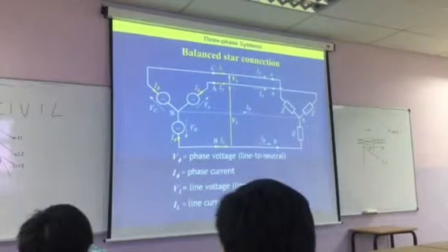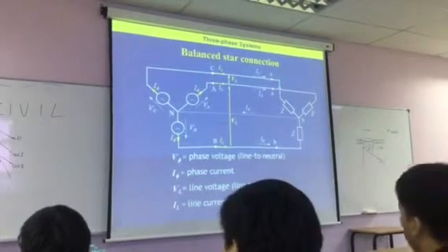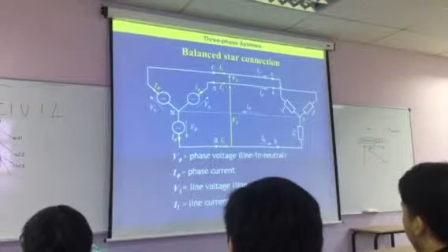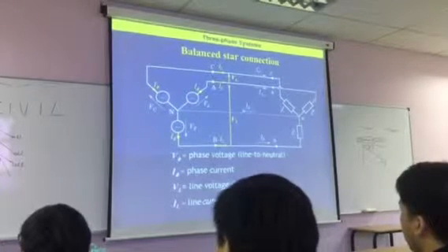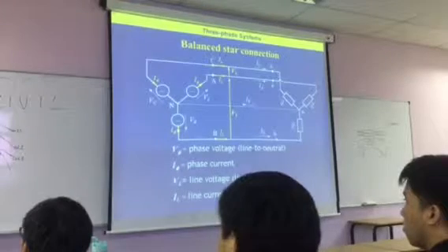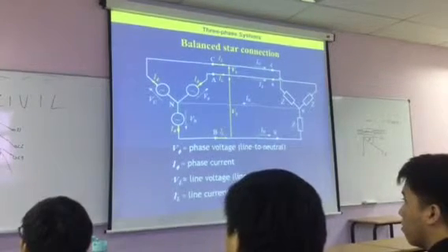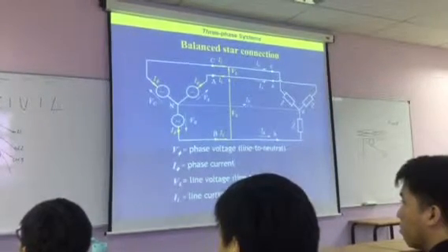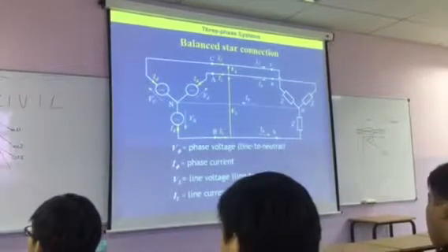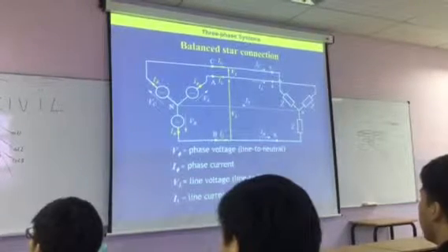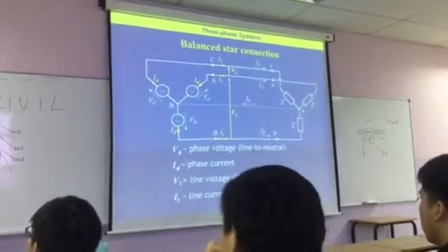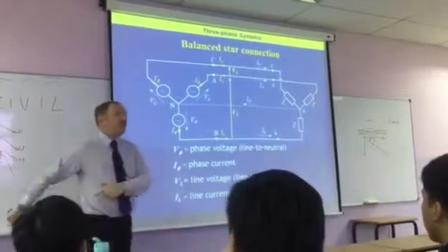Now, because the Malaysian low voltage distribution system is similar to the UK, how many volts AC do you get out of a power socket in your house? 240. Is it still 240? Ish. I think in the UK it's come down a little bit, it's probably nearer 230. The three phase is normally 415. But of course, you only see one phase, so only one phase comes to your plug.